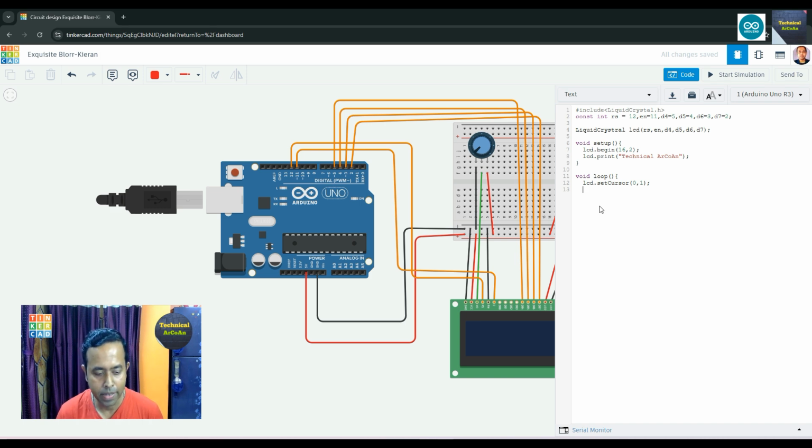Okay, and here we just display some seconds, and here I am using a built-in function millis, which actually returns the number of milliseconds, and we divide by 1000 to get seconds. Okay, so just write here lcd.print and use the inbuilt function millis and just divide by 1000, means we get in seconds. Okay, and then we just complete our sketch. So just close our loop.